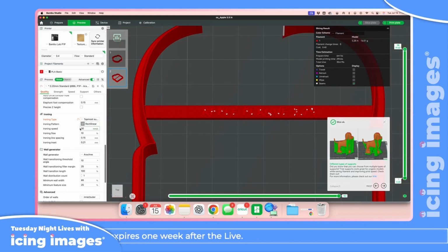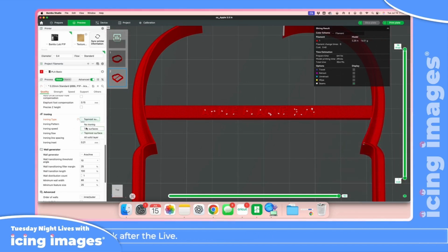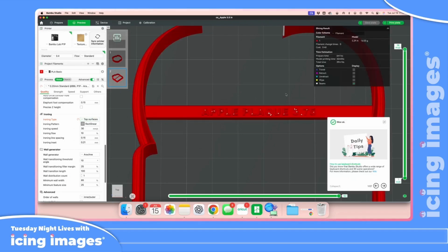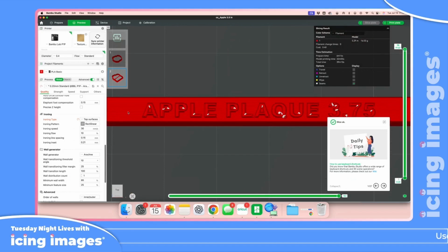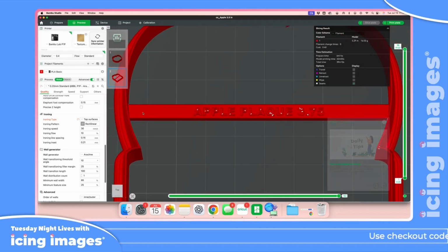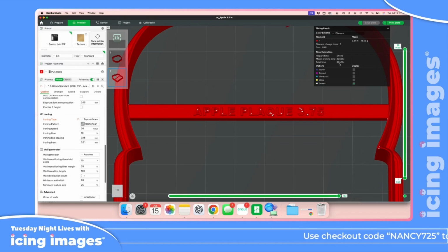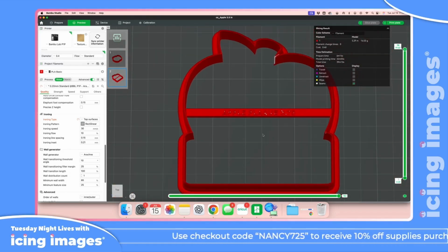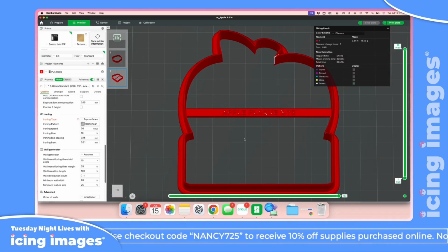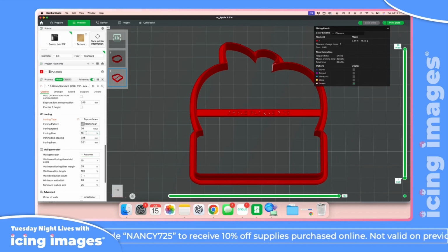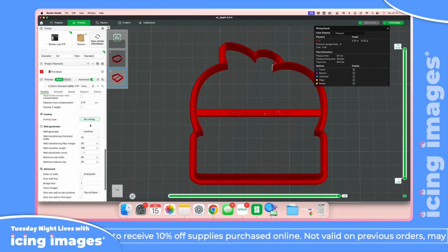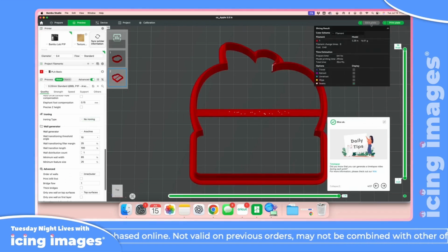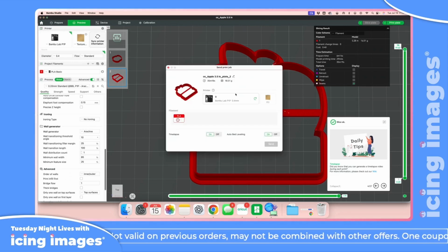That didn't really help that much. Let's do top surfaces. All I know is when I iron things, it's smooth. There we go. It smoothed it out just a little bit across here, and it will take a little more time. You don't have to turn on ironing, but you can if you want to smooth the top surface out. But I don't think that's necessary, so I'm just going to go back to no ironing. And then I will click slice again, print plate.